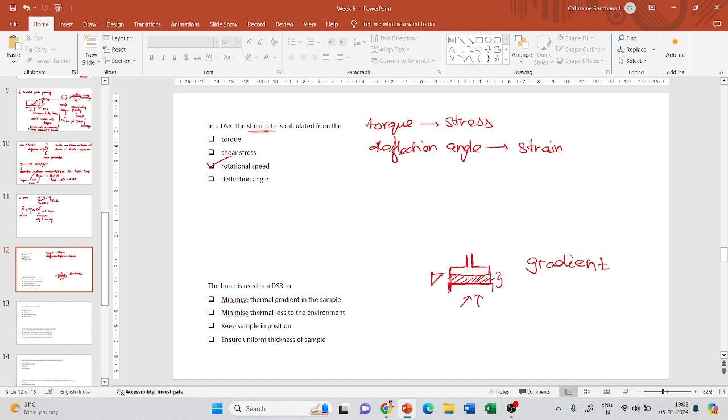Okay. So in that case, if you see ASTM D7175, they would have mentioned how to eliminate this, or how to make measurements without the artifact of thermal gradient. So what usually you have to do to ensure that your sample does not have thermal gradient is you have to allow a considerable amount of waiting time to the sample so that the entire sample attains thermal equilibrium.